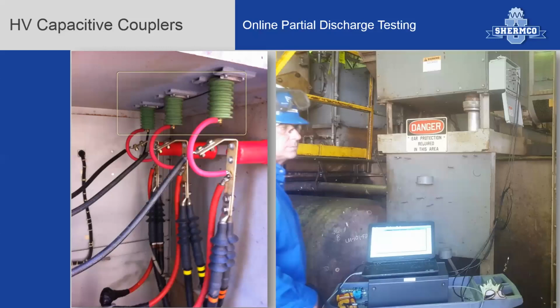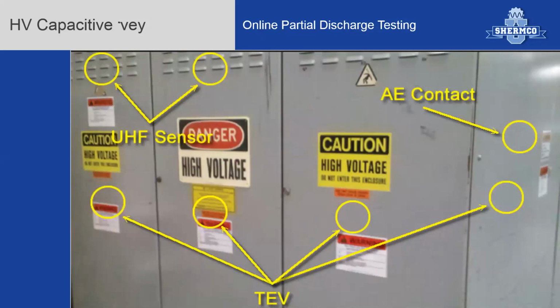All right, let's move on to some samples of surveys. Here I show a sampling of switchgear survey, and I'm showing the rear panel of the switchgear lineup, because this is typically where the medium voltage bus or the high voltage bus is running. This is possibly where the circuit breakers are racked in and seating onto the bus. It would be most advantageous to pick up at the rear panel of the cabinets. This also could be where the incoming or outgoing cable landing compartments are located.